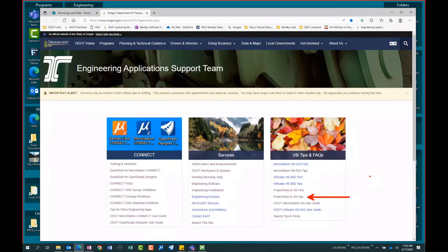So there's a little bit of help that the naming tool needs from you when you're naming your files. And that little bit of help is to just always end all of your document names, especially if they're DGN files, with a .dgn. I will show you that several times as we go through.